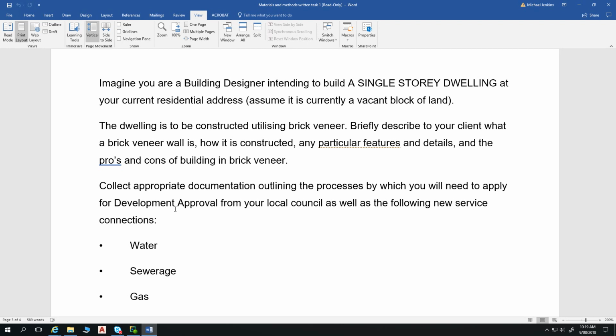So 76, 110, and 230 is your standard brick size. That's something I also hope you'll learn fairly soon in this course, because the standard size brick has a lot of flow-on effects to the design of buildings and the size of windows, size of doors, all these types of things, and we'll go through that later on.